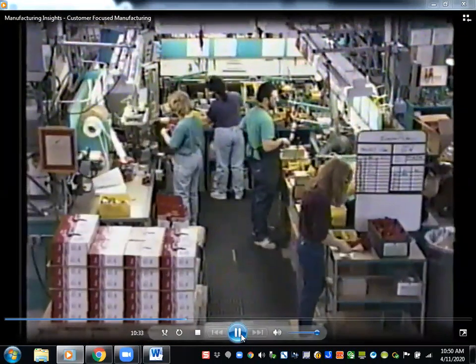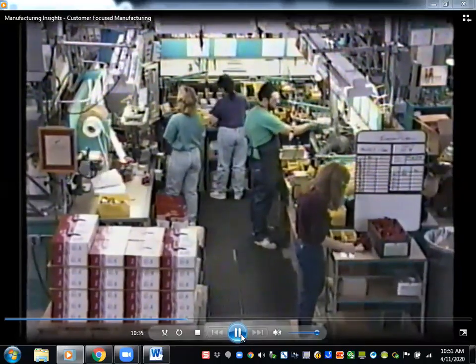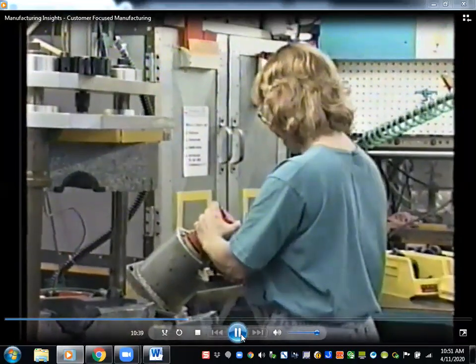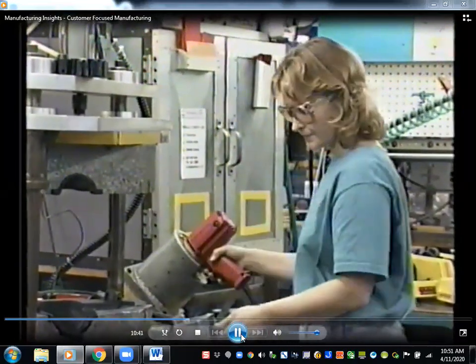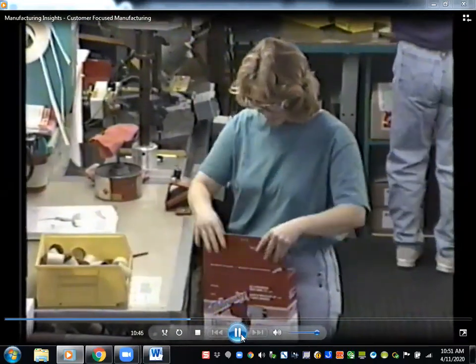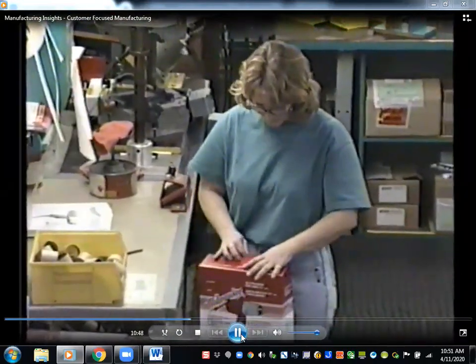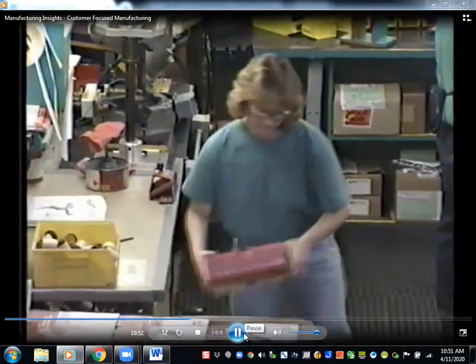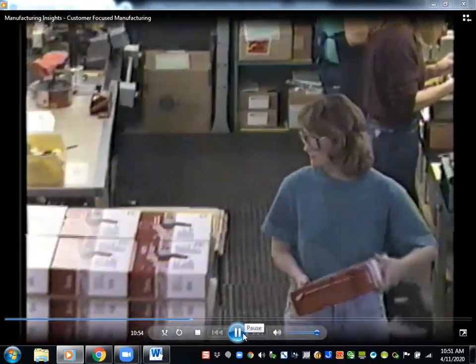Machine and operation within easy reach of all cell members. Parts and assemblies move in a counterclockwise direction, one at a time, eliminating inventory buildup between successive operations. When a finished part or assembly arrives at the last station in the cell, it is complete and ready for shipment, either to the customer or to another cell.